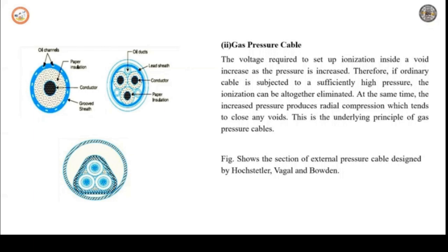Advantages: the thickness of insulation required is less, hence the cable is smaller in size and weight. The thermal resistance is less, hence the current carrying capacity is more. The possibility of voids is completely eliminated. The allowable temperature range is more than solid type cables. There is reduced possibility of earth fault, because in case of any defect in the lead sheath, oil leakage starts, which can be noticed before an earth fault occurs. Perfect impregnation is possible with this. These are the few advantages.